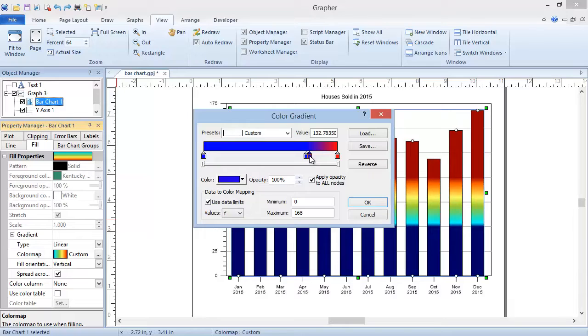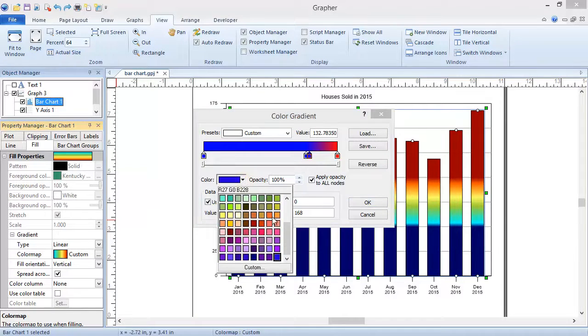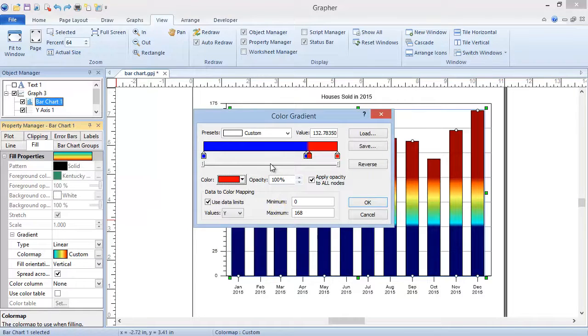Click on the new node, select red from the color drop-down list, and set the value to the mean and add an extra 1 to the end of the decimal place, so the second node appears on the correct side of the first. Delete the 1 at the end so they are exactly the same.